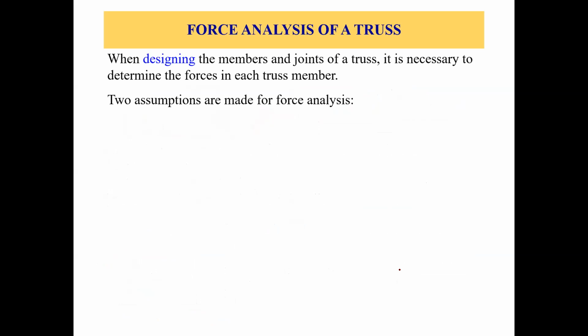Okay. Now next is force analysis of a truss. Why do we need force analysis? We already discussed it. We need to make sure that the member is safe, and the whole truss is safe. When designing the members and joints for a truss, it is necessary to determine the forces in each truss member. Force analysis is to determine the internal forces in all the members of the truss.